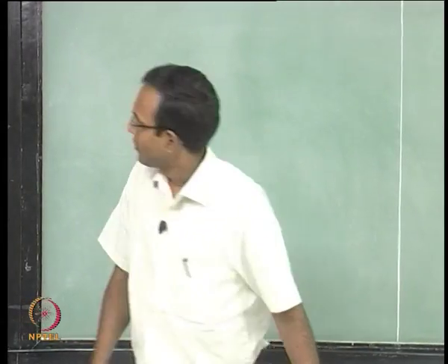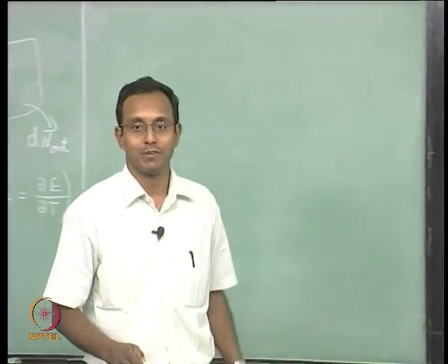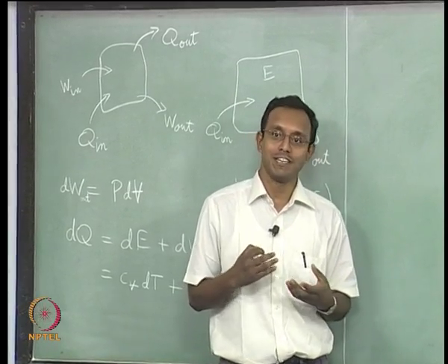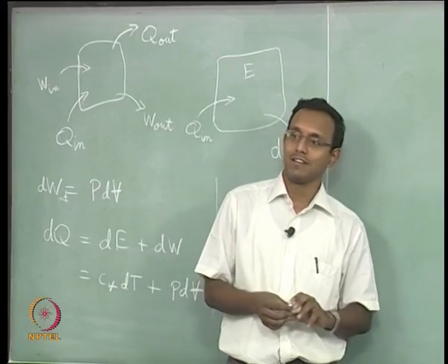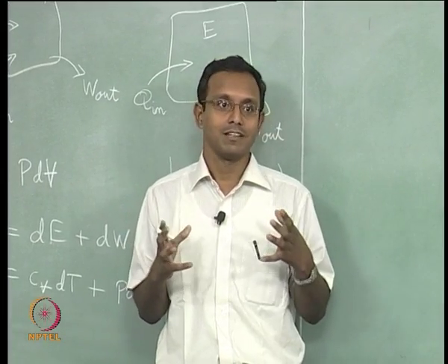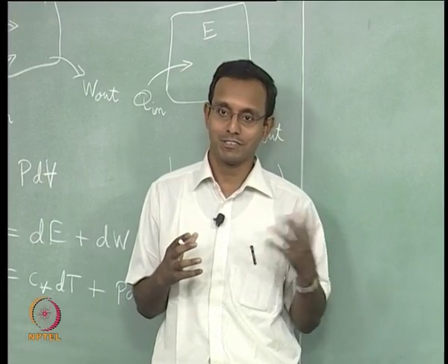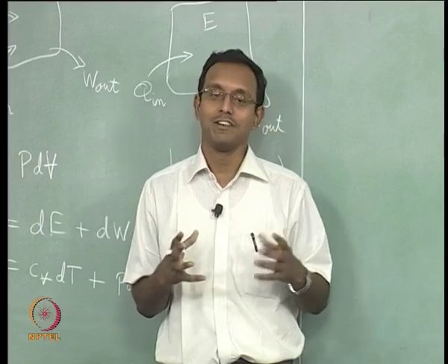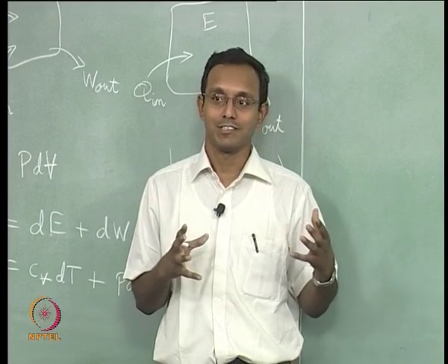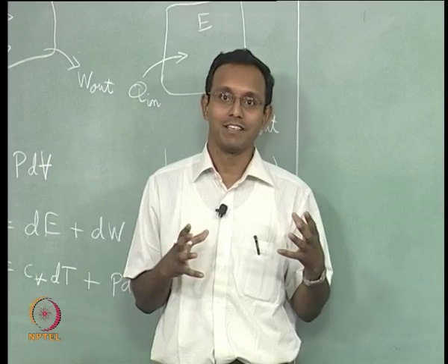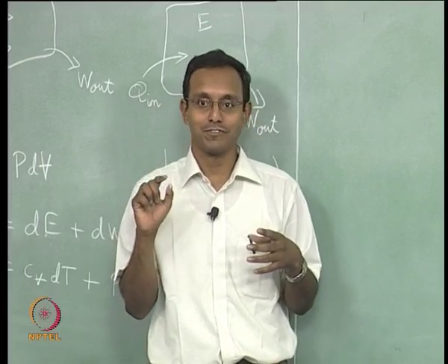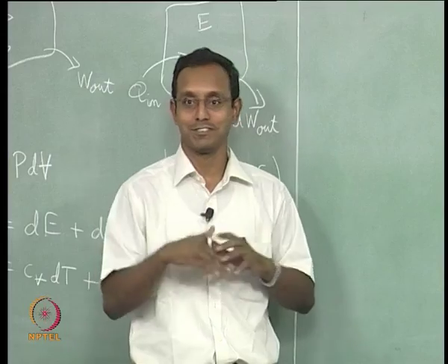Okay. So, now if I go and talk about the second law of thermodynamics, we said entropy is a quantity which always increases, but when we write it mathematically we think of it as there was some net energy interaction with the outside world, and then that energy interaction, if it is an irreversible process, then if it is a PdV work it can be reversed. If it is a heat interaction it cannot be easily reversed. Okay. So, we are thinking about heat interaction with the outside world, and then we will say for such an interaction entropy is given by dq by temperature of the system, actually it should be temperature at the interface.